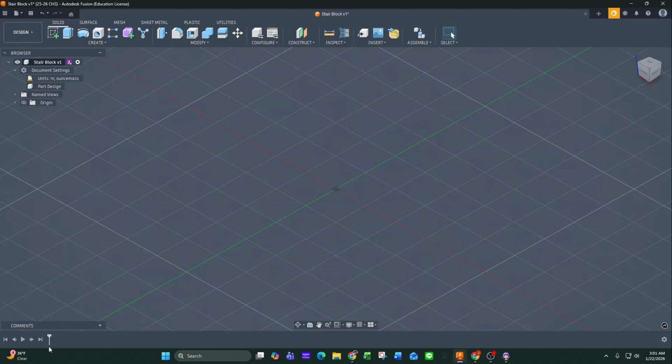So I'm going to go ahead and just delete everything. So my timeline is now blank. I went through and just deleted everything. This is letting me start from scratch. Your best practice, mentioned this before, is always to have as minimum amount of steps in your timeline as possible. That's why everything that you can should be in the same sketch, and be very specific, not just sketching and having a very busy timeline.